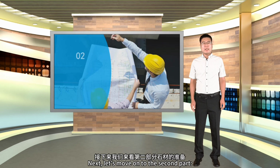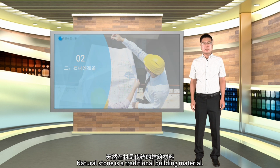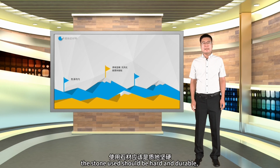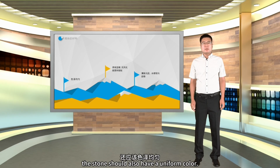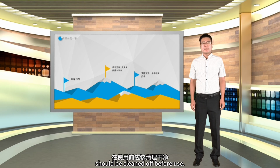Next, let's move on to the second part, preparation of stone materials. Natural stone is a traditional building material. In masonry work, the stone used should be hard and durable, free from weathering, flaking, or cracks. For exposed stone walls and columns, considering the aesthetic requirements of the finished product, the stone should also have a uniform color. Any contaminants such as mud on the stone surface should be cleaned off before use.